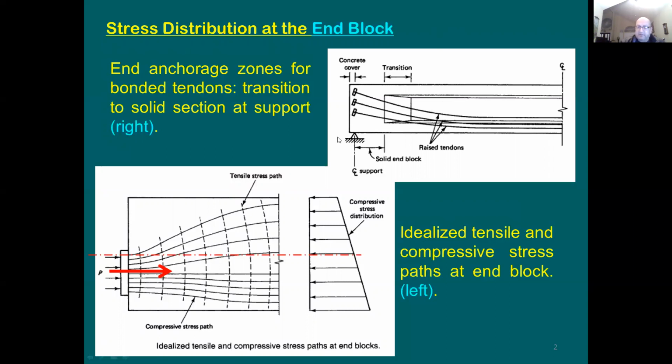The strands here are going to be 100% bonded to the surrounding concrete. After the concrete is hardened, you trim the strands from each side of the beam, and with that you start to transfer the force from the strands to the concrete itself. Now, the transfer of this force from the strands to the concrete is going to happen throughout the surrounding concrete to the strand itself.